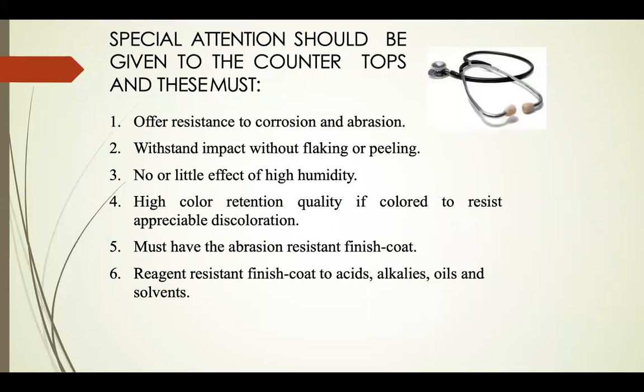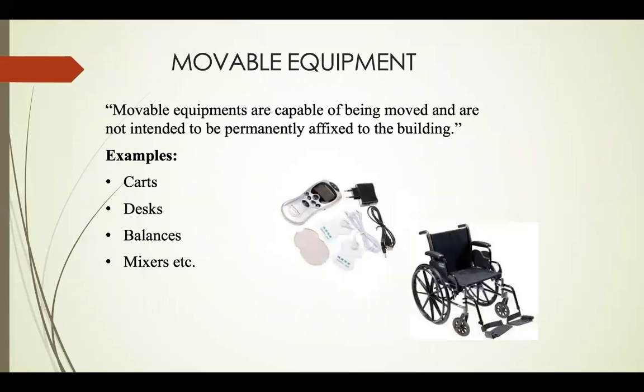Special attention should be given to the countertops, and these must offer resistance to corrosion and abrasion, withstand impact without flaking or peeling, have little effect from high humidity, have high color retention and resist appreciable discoloration, and have an abrasion-resistant finish coat, resistant to acids, alkalis, oils, and solvents.